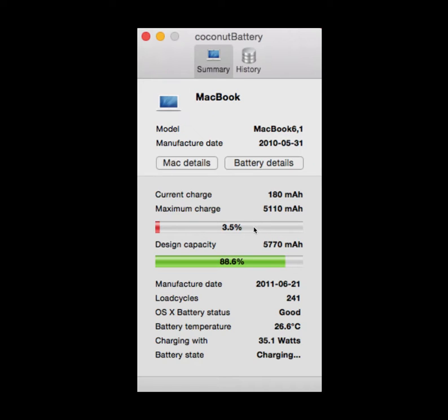And once it starts accumulating, it should start jumping up by about 10 or 12 milliamp hours every, I don't know, 15 seconds. And if it's a good battery, it will keep doing that all the way up through the end of the charge. If it's not a good battery, it will just not charge at all, or it will start accumulating very slowly, like 2 or 3 at a time, which generally indicates that it's not going to get there. A good battery should charge fully in a matter of 2-3 hours. A battery that takes 15 hours to charge, definitely be suspicious of that battery. But this one's looking good.